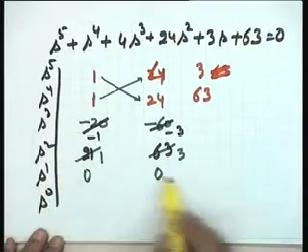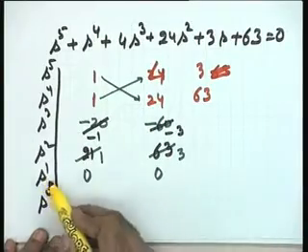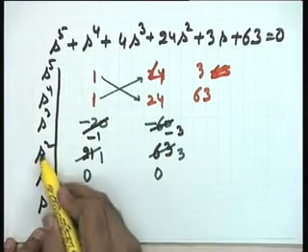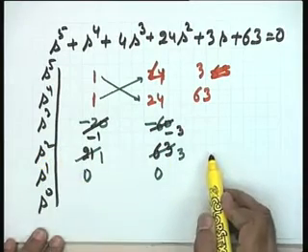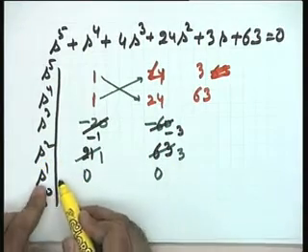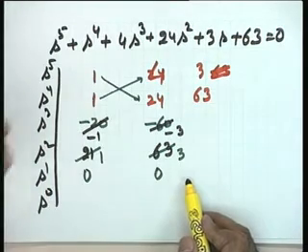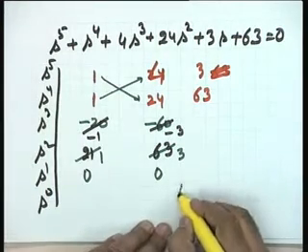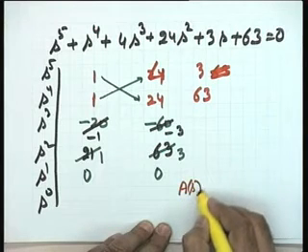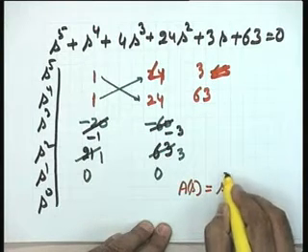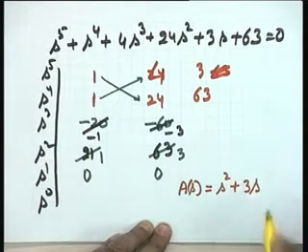To study that I come back to the Routh array we have formulated. You see that this is an S1 row, you go one row above and that is the S2 row. When I get an all 0 row, I construct an auxiliary polynomial, and the auxiliary polynomial for this example is s squared plus 3.